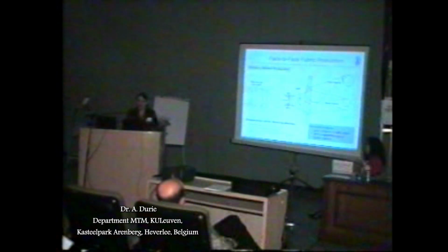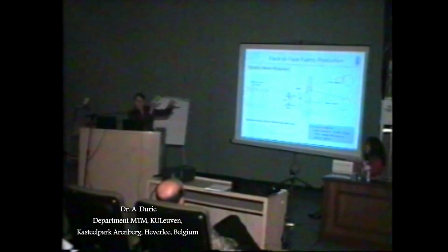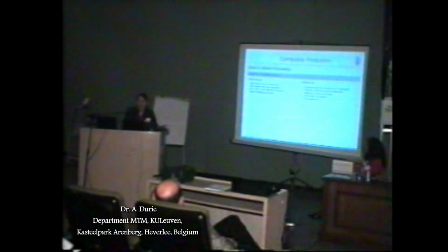What we do to manufacture this product, and this is actually the preform that's used to make it, is we have a couple of process paths that are possible. The first one is that we can just pour a liquid resin over the preform and roll it in with a paintbrush roller or a paint roller. The resin goes into the pile yarns and they become quite stiff. So the two layers of fabric, instead of being compressed together, actually separate to form a sandwich pile. This method is extremely good for piles that are fairly low height, up to about 18 millimetres; 16 to 18 millimetres is okay.